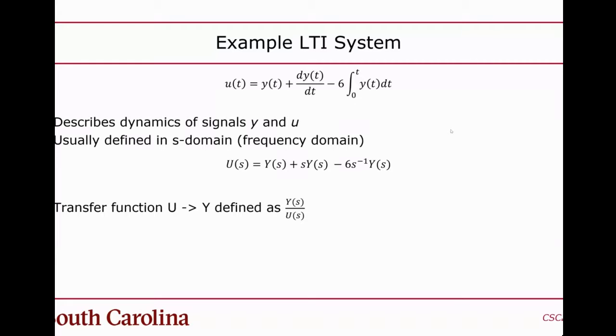Okay, so now you want to build a transfer function. The transfer function is the point at which you start to define what the inputs and outputs are. Even in the Laplace domain, you basically just have an equation describing the dynamics between these two signals. But when you put these into a transfer function, that's when you start to conceptualize this as a block that you can put in a block diagram, like a component, a module.